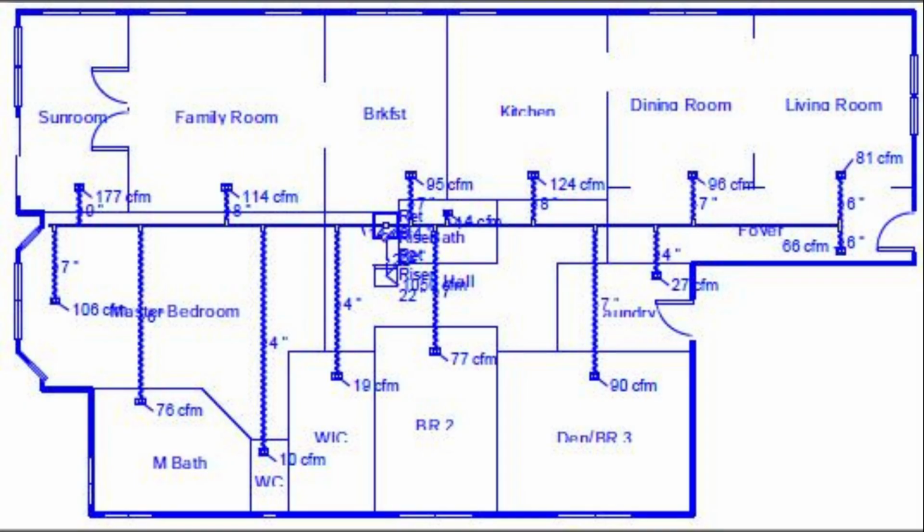Equipment sizing. Size equipment in accordance with Manual J and the Energy Star HVAC System Quality Installation Checklist. Duct sizing. Use ACCA Manual D to size ducts based on Manual J loads. Duct installation. Sealing. Tightly seal all duct connections and joints with mastic and test to confirm a leakage rate of not more than 5% of total system airflow.